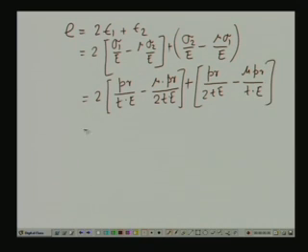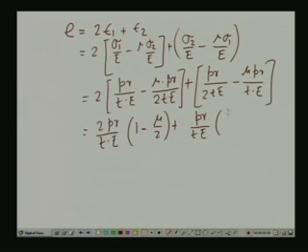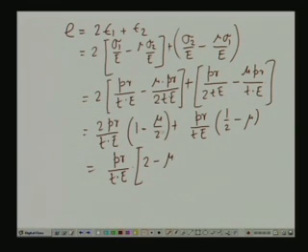So, this is equal to, if we take out P r by T, twice P r by T E times 1 minus mu by 2, plus from here if we take out P r by T E, we have half minus mu. So, if we take out P r by T E for the whole, we have 2 minus mu, this 2 gets multiplied, plus 1 minus twice mu by 2.